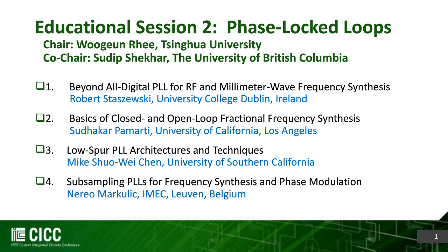Yeah, absolutely. When you do the cascading, as you can see, the critical path of that digital subtraction logic will unfortunately keep increasing. So it is absolutely correct. We have to be mindful that whatever that cascaded logic is, it will not exceed the timing constraint of that digital block speed. So typically for the digital PLL, the digital block is clocked by the input reference frequency. So that's just one thing that we need to be careful about: we need to make sure that we can still complete the computation within the period of that reference clock.